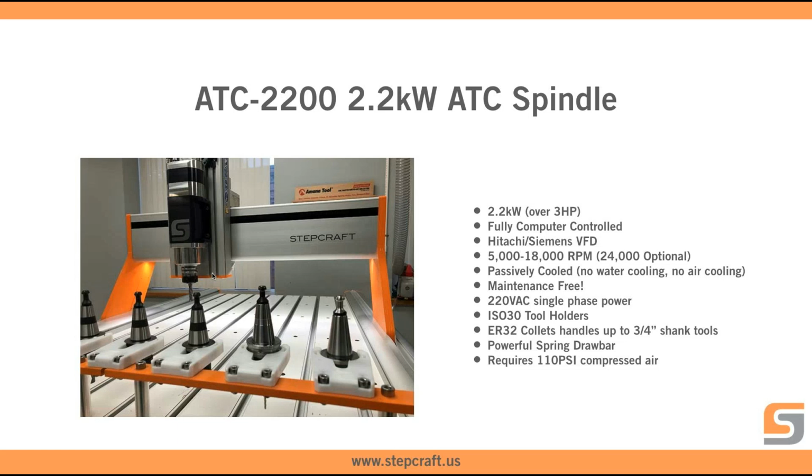This is a passively cooled spindle. Everybody at trade shows, it's funny, everybody's like, what does that mean? Basically, there's no water cooling and there's no air cooling. It's completely sealed. That usually puzzles a lot of people, especially at a show, because spindles are supposed to have either water or air. And everybody asks, well, how does this thing stay cool? The case design on this spindle is designed to dissipate heat very quickly. The average operating temperature after, say, a 12-hour day of machining continuously, like a long carving, is right around 105 to 110 degrees Fahrenheit. So you could touch this thing all day long and you're never going to get burned. It doesn't overheat.